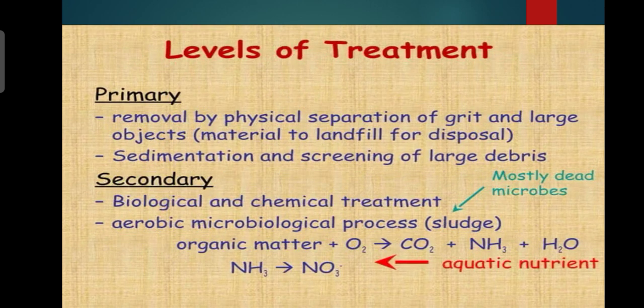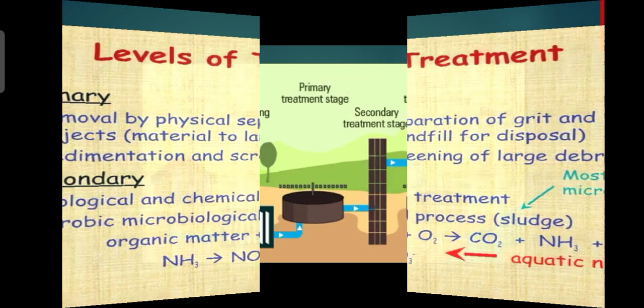Primary: removal by physical separation of grit and large objects, sedimentation, and screening of large debris. Secondary: biological and chemical treatment, aerobic microbiological process.